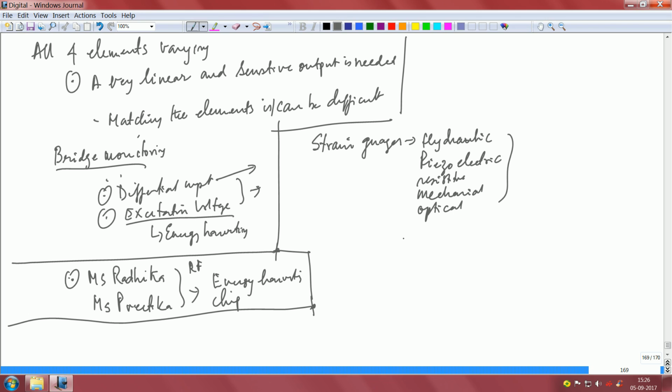Okay. Now, the strain gauges, so basically it is a resistive element, right. You can have the strain gauge R value varying from 30 ohms to about 3k ohms. It can be up to as high as 3k ohm, and higher the resistance value, good for the energy harvesting applications. For energy harvesting apps, higher the R value better, because the current consumption will be low, will be minimal, right. So, it is good to have a higher value.